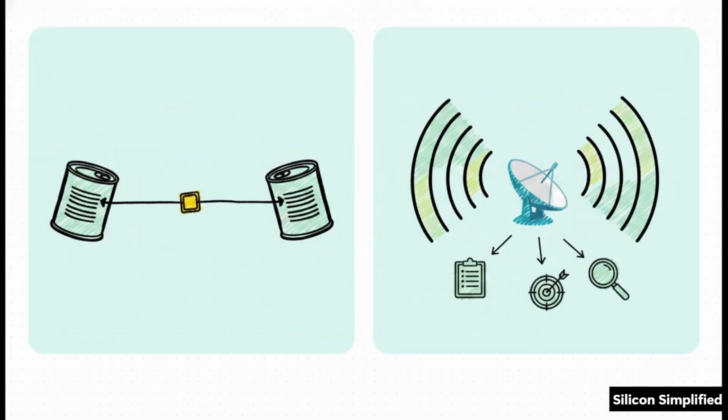And this actually brilliantly illustrates the difference between standard TLM ports and analysis ports. Standard TLM ports are point-to-point. You have one producer communicating with one consumer using put, get, or peek operations. But an analysis port, that is a one-to-many broadcast. It uses a single non-blocking write function. This means a single monitor can connect its analysis port to multiple subscribers, like various scoreboards and coverage collectors, and just blast that transaction out to all of them in the exact same zero-time delta cycle. It keeps everyone perfectly updated without missing a single beat.